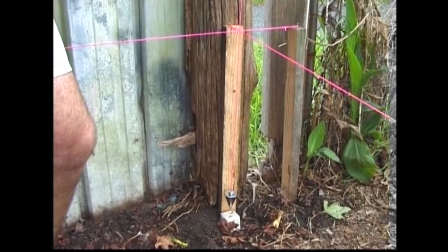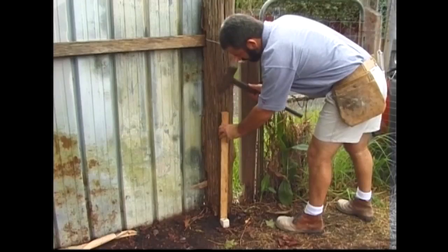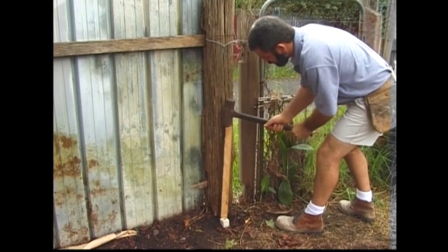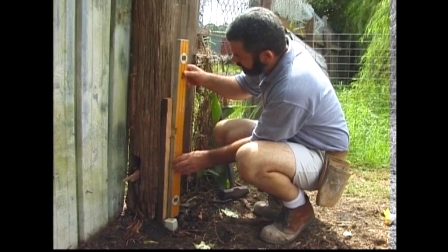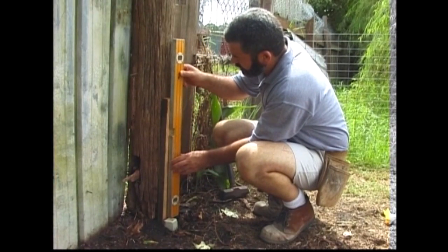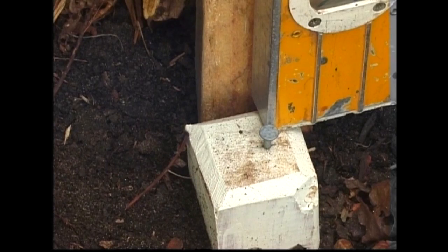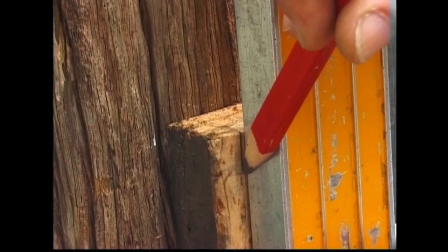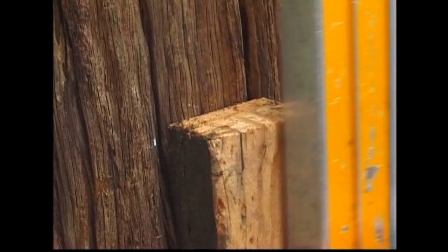The side boundary is established as a datum or starting point by running a string line directly above the 2 survey marks at the corners of the block. This boundary string line is fastened to pegs driven into the ground behind the survey marks. The string is plumbed to the marks to make sure it lies vertically above them.